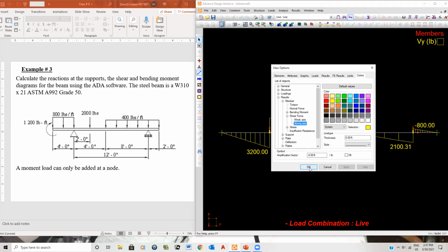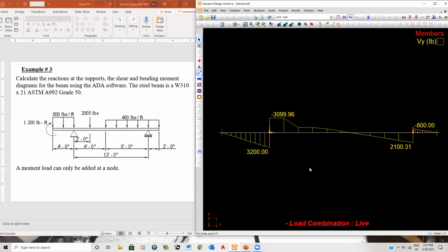And it makes sense because according to our sign convention, if the left side is going down with respect to the right side, therefore it should be negative. You follow? Now, don't worry, this is what you really have to look at. This is 0 here, but there's really no negative or positive shear. There are negative and positive moments. In other words, it tells you which side the tension is on. But as far as shear goes, is that clearer?